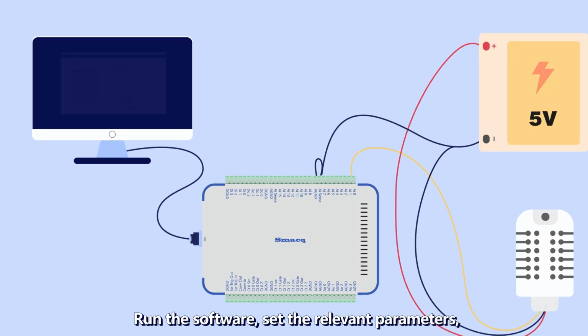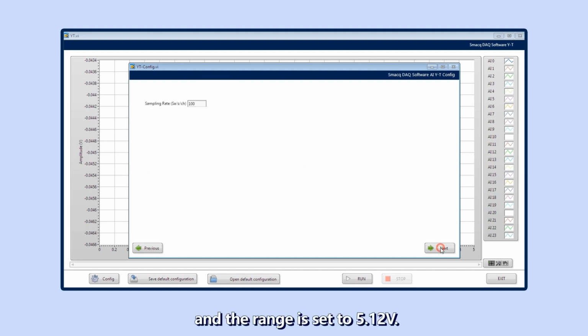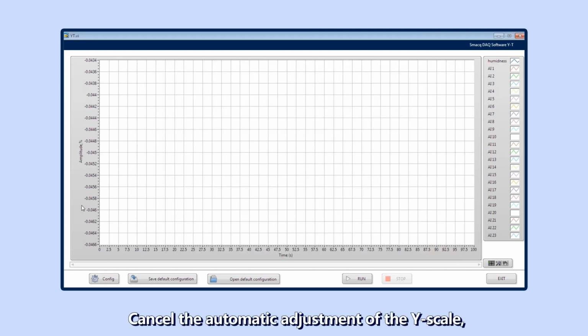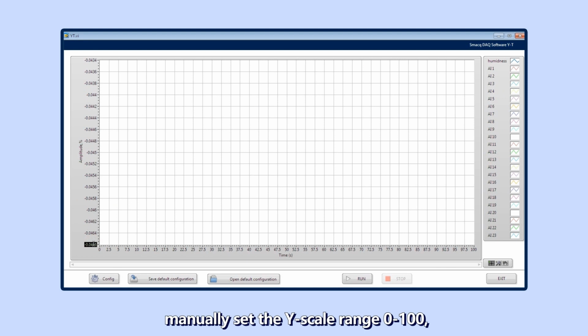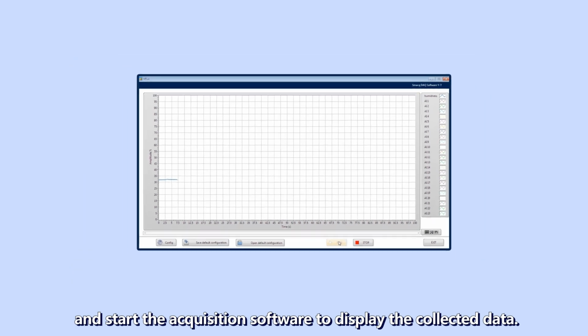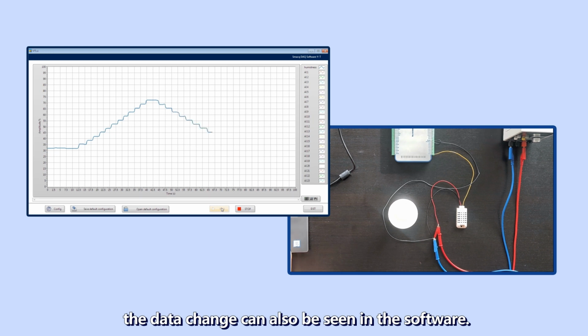Run the software, set the relevant parameters, and check the AI0 channel. The channel comment is humidity. The sensor output is 0 to 3 volt, and the range is set to 5.12 volt. Because the sensor output rate is low, the sampling rate is set to 5. Take the unit conversion function and set the sensor's unit. The output voltage upper limit is 3 volt. Other settings remain unchanged. Cancel the automatic adjustment of the Y scale. Manually set the Y scale range from 0 to 100, and start the acquisition software to display the collected data. When the ambient humidity increases, the data change can also be seen in the software.